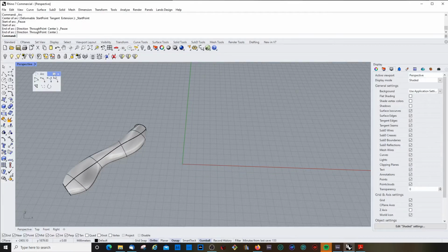And the last one here in this upper list is start, end, and then radius. Start point, end point, and then you define the radius, either by snapping to something or by just putting the radius 200. And then it tells you it's too small. Because of the distance between the start point and end point, the radius needs to be at least 765.82. So let's say 800. Okay.